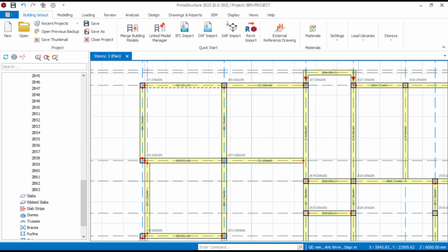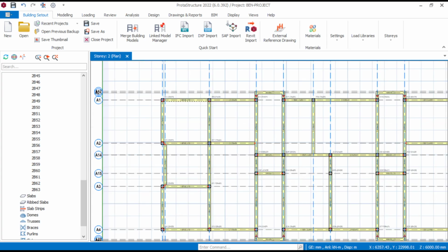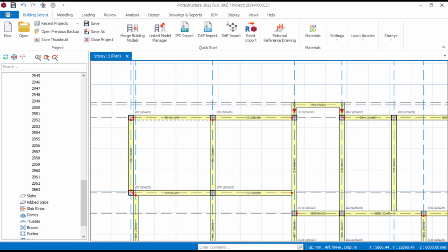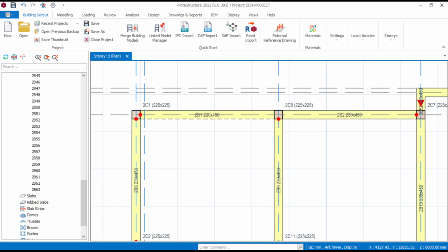Now, because it's a roof, it's a rectangular beam, it's not a flange beam. So what we can do is to make the roof beam to be 300. Let's make it 300. It's just a rectangular beam. It's not having any slab. It's not sharing any slab load or anything. So let's now change this.